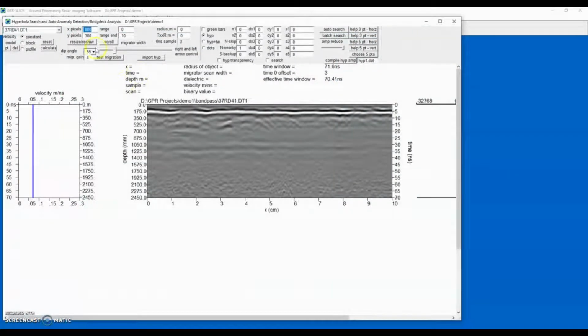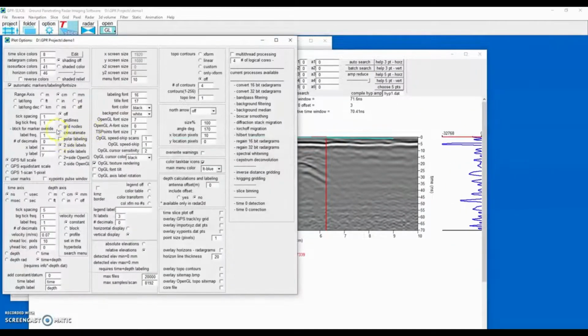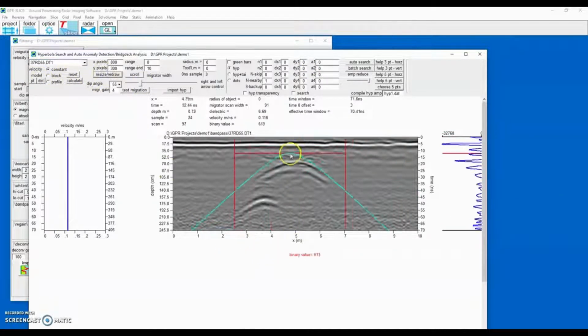We're going to go to the search menu, and I'm going to put on radargram number 55. And first of all, if you don't have a hyperbola showing, you have to set the correct unit. And I'm going to set this to meters here, and then centimeters. And then we come back down, and then we have the correct unit that could be shown here. I'm just going to redraw the screen. Besides redrawing, we have meters. So there we're matching the hyperbola.